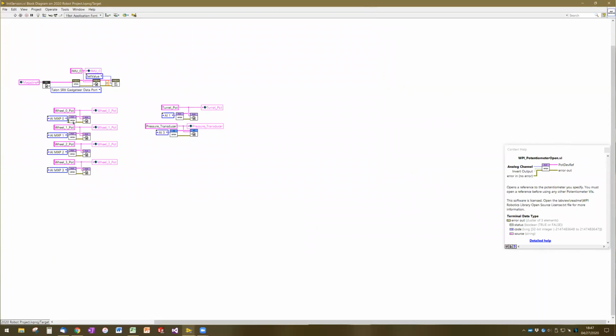One advantage, which is sort of minimal, is that it rescales it from 0 to 1, which may or may not be easier for you to work with. The other nice thing is that technically this also does a check for you. The wheel encoder actually doesn't have to give between 0 and 5 volts. Depending on how it was manufactured, it may only give between 0 and 4.8 volts or some other random value.